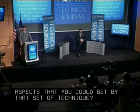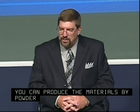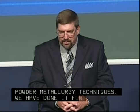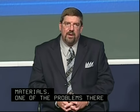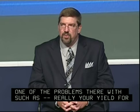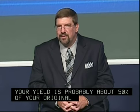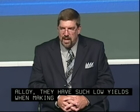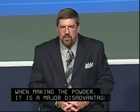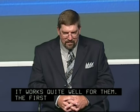You can produce these materials by powder metallurgical techniques. We've done it for one of the high temperature shape memory alloys, a nickel, titanium, palladium material. One of the problems there is the yield for your powder processing. Your yield is probably about 50% of your original melt. So when you're working with these precious metal containing alloys, to have such low yields when making the powder is a major disadvantage, but you can produce these materials through conventional powder metallurgical techniques, and it works quite well for them. The first question, I don't quite understand what you're asking about in terms of the hysteresis of the strain.